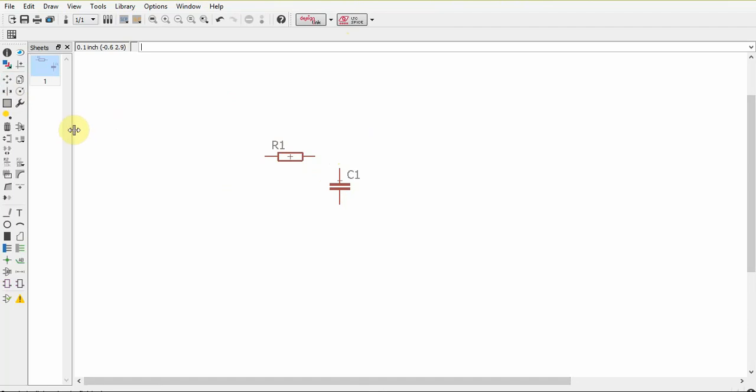If you want to connect two parts, you would click on wire, or I would actually suggest doing a net, because that one shows you the connections between various points clearly. But in this case, wire would be sufficient. We'll do a net just to be consistent with what I was saying. So that's a net, and then you could also extend this like so.